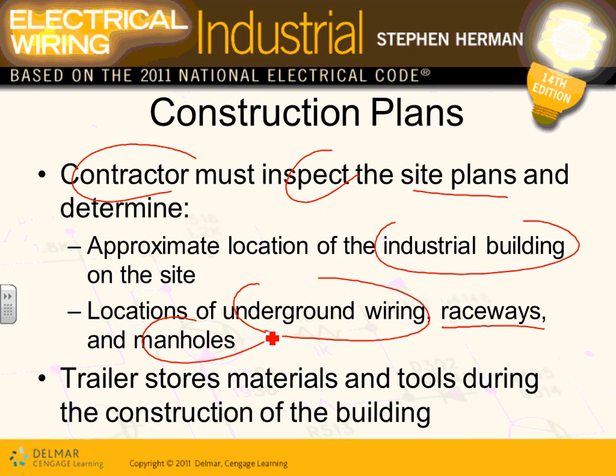So when it comes to the site, very, very important. I don't know if you guys can see them right in here. Some of the homework questions will tell you the location of the manhole. Right here. Here's the manhole. So where's the phone? Here's the phone. So looking at the site and identifying the location is so important, guys, for us as electrical engineers and electricians and estimators.